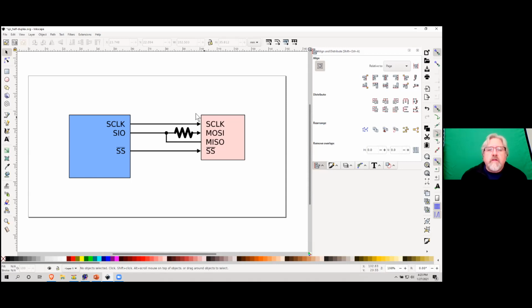We configure it like this because it's a half duplex device. You send it a channel you want to read, and then you give it more clocks, and it will output the value from that channel. But, as with other chips it can do, you're not sending and receiving at the same time. So we cut down on the number of IO pins used.